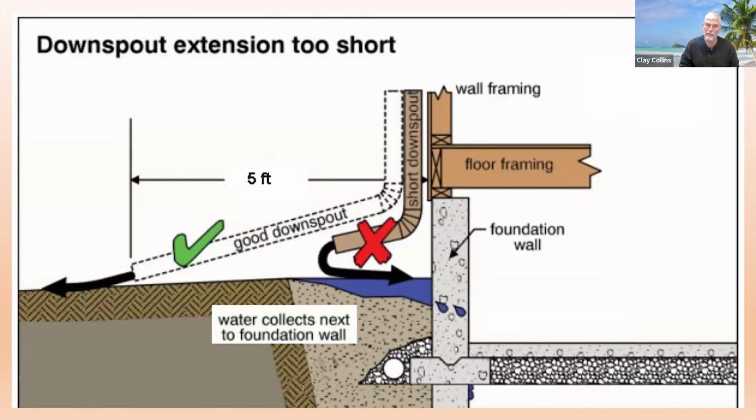I think gutters would be a great benefit, but the problem still is, you look at that 5 feet away, and how many times are you going to trip over it, mow around it, hit it with your string trimmer, or do something else to damage it, to get to the point the homeowner's simply going to do away with it. I think the absolute best solution is that it goes directly down into the subsurface drain. But that's money.